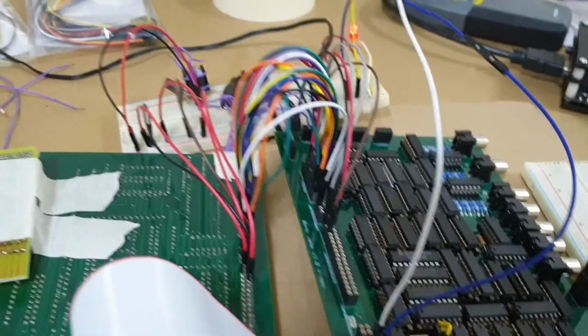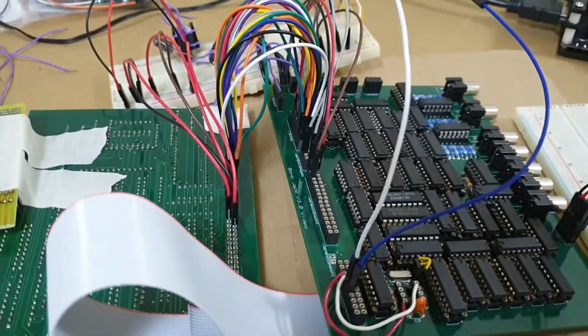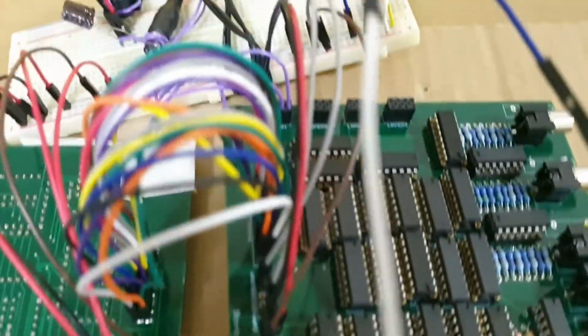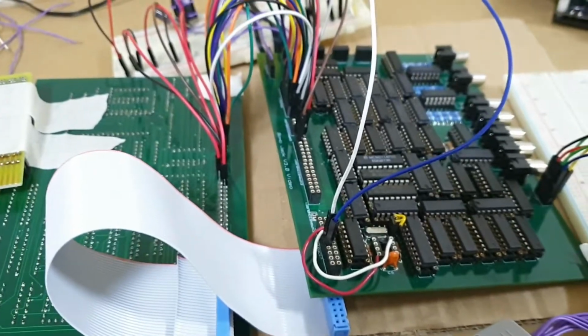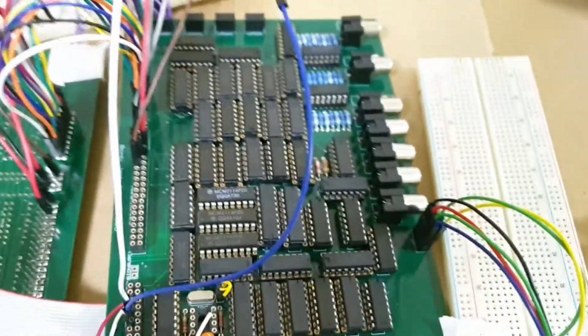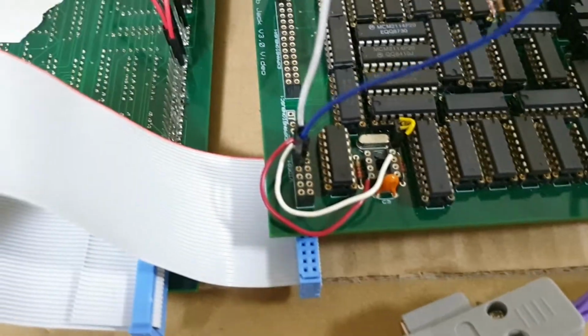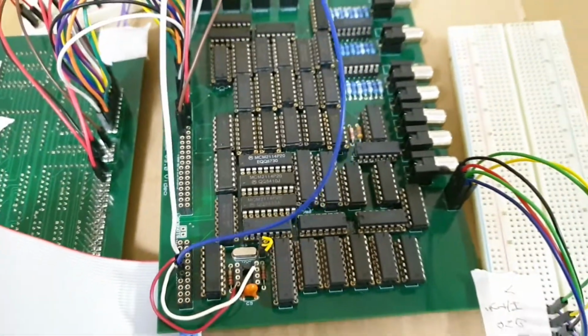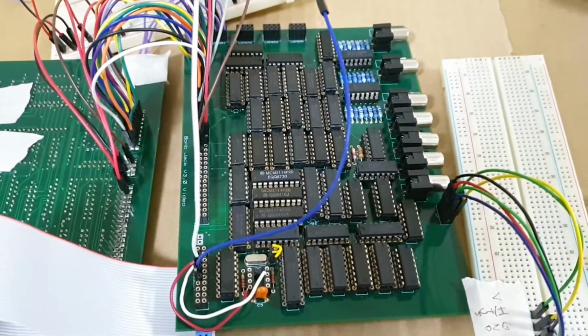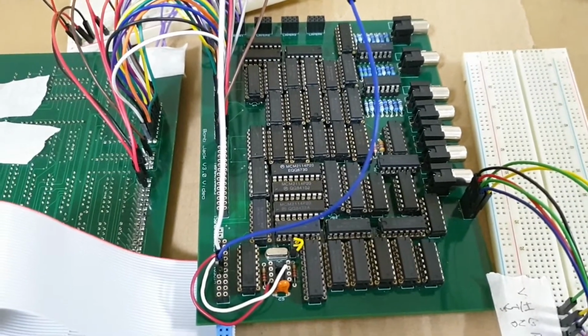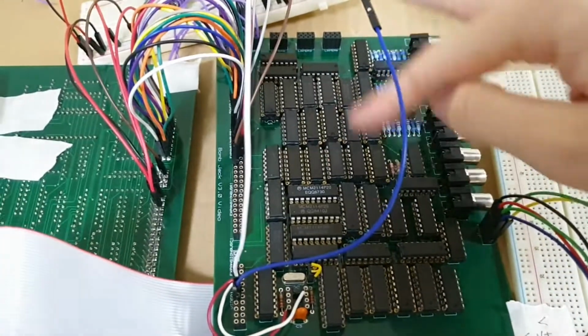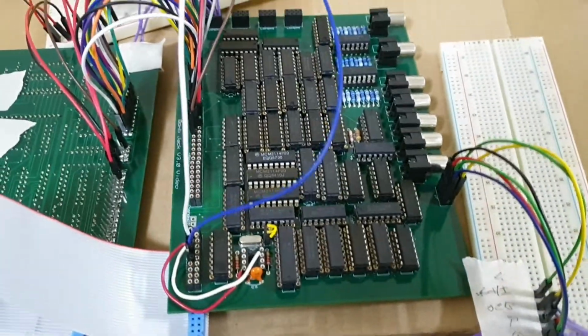The only parts that are not auto placed on these PCBs are the output circuitry here with the resistor ladders and the common headers here and the pixel headers. Those were placed by me, obviously, because I want to make sure that they're in consistent places, but all of the other components pretty much were auto placed. Oh, the clock timing as well was explicitly set out by me, as best as I could with my limited, almost non-existent analog electrical engineering knowledge. But the rest of the PCB, all of this stuff in here, was automatically placed and automatically routed.